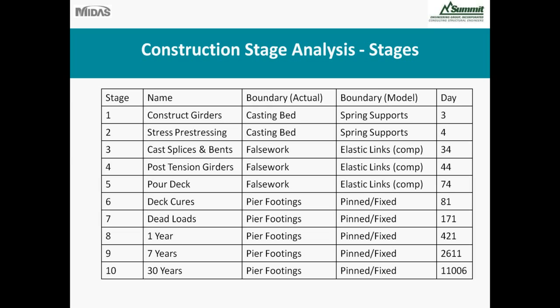The alternative option here is to use vertical restraints, run the model, and analyze whether or not the restraint was restraining the girder in a downward direction, and then rerun the model, releasing any of those that were restraining the girder downward. Shoring towers won't ever hold a girder to the ground. It can only keep it from deflecting. And then once we get into the deck curing, it's just the pin to fix connection of the piers.